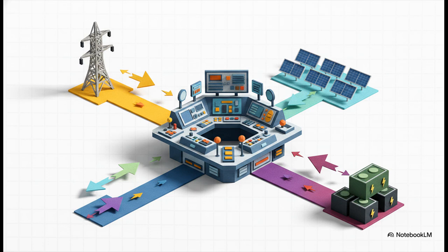And tying the whole shebang together is the BES controller, which gets its marching orders from the Operator Control Room subsystem. Think of this as the brain of the operation. It lets operators dynamically adjust modes between peak shaving and charging based on real-time conditions, masterfully orchestrating the flow of power between the grid, the solar array, and the battery.